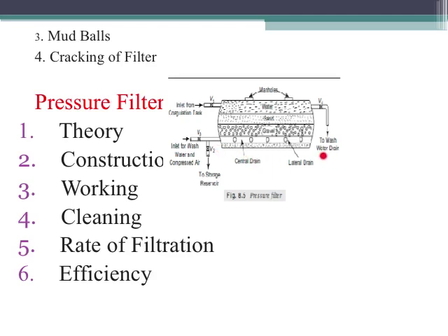So how about the working? In normal working condition, the valves V1 and V2 are kept open and all of the other valves are kept closed. The water enters the chamber through the inlet pipe, and from the top it passes through the filter media under pressure. The filtered water is then discharged to the outlet pipe and stored in a storage tank.